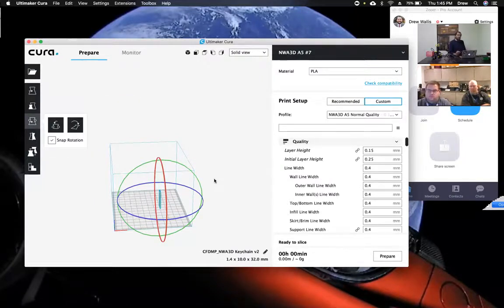And rotating is important too, because you want to make sure you have the correct print orientation for your model. So if it's at a weird angle or off to the side, it might have to print with supports. But if you rotate it in a certain way, it might not need to make as many supports. So even though those are automatically generated, and I'll show you here in a second how to turn those off if you would like, you can flatten stuff out.